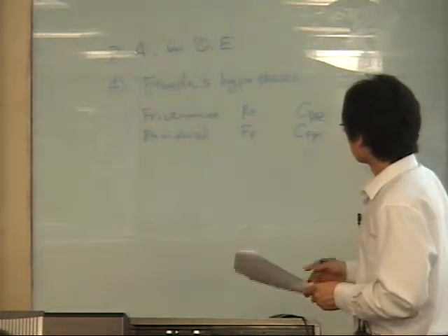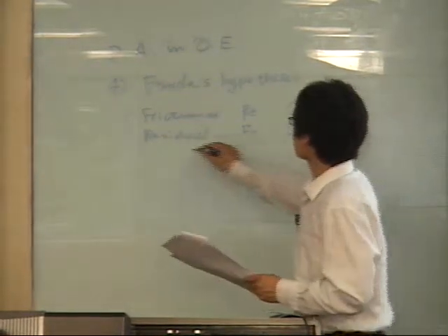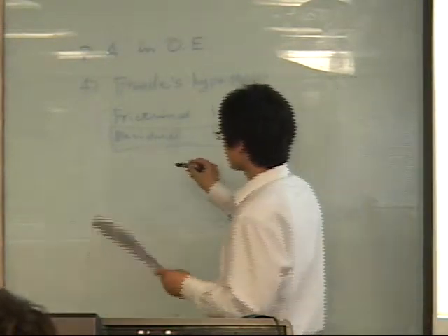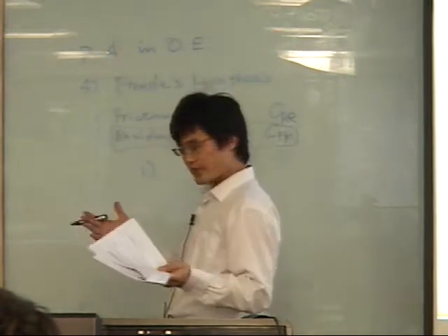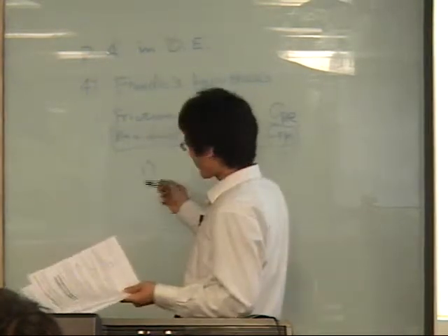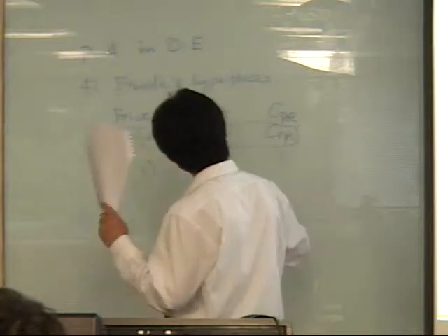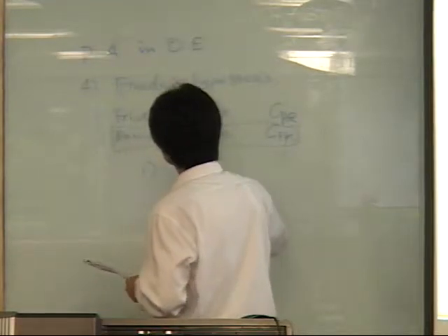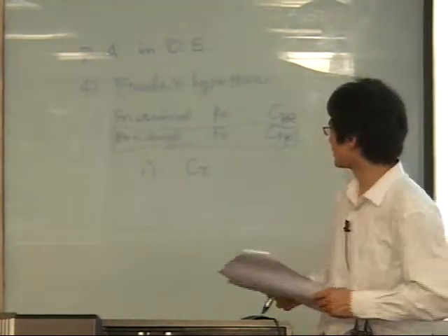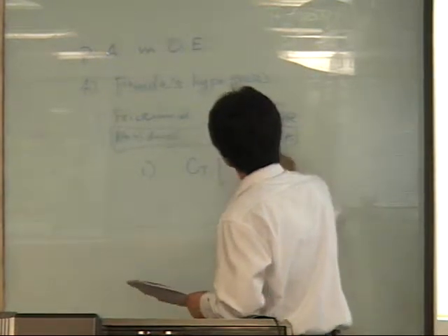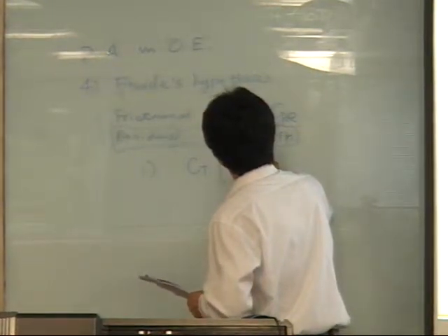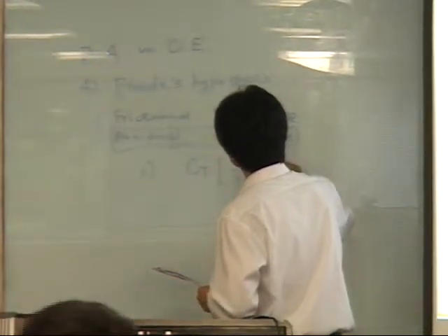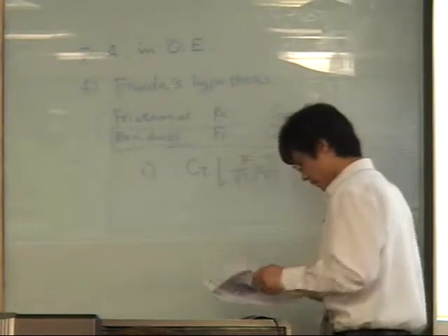So when we do experiments, we match the Froude number. The standard procedure would be: we do a towing test, we figure out the total resistance. We express it in terms of a coefficient, C_T. You can easily figure out it would be a force over rho U squared L squared or something like this.